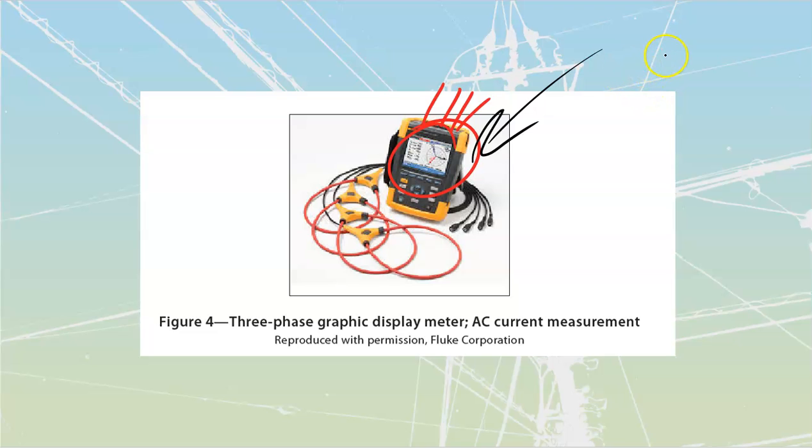And you're going to be able to store them based upon the millisecond or things like that, which is going to give you a lot more data than what you have off of your power loggers, which are going to be much further spaced apart. With the power logger, you can say, I want to get a voltage every minute, and so you get a long runtime. You can leave that going for a week. You're going to take a voltage and a current reading every minute, but you're not going to see transients or surges or things like that. You're just going to see the overall system, how it's being used.